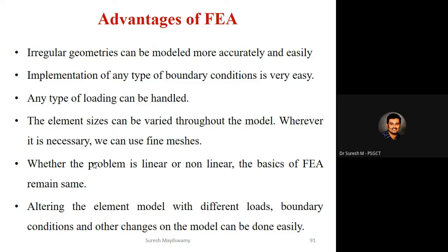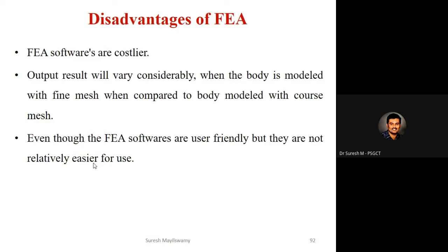But we have some limitations in this software. Disadvantages of finite element analysis. First, FEA software is costlier. Output results will vary considerably when the body is modeled with a fine mesh compared to a coarse mesh. Of course, because the analyst should know where to do the fine mesh and where not to. That condition the analyst should know, and then only will we get an accurate result.